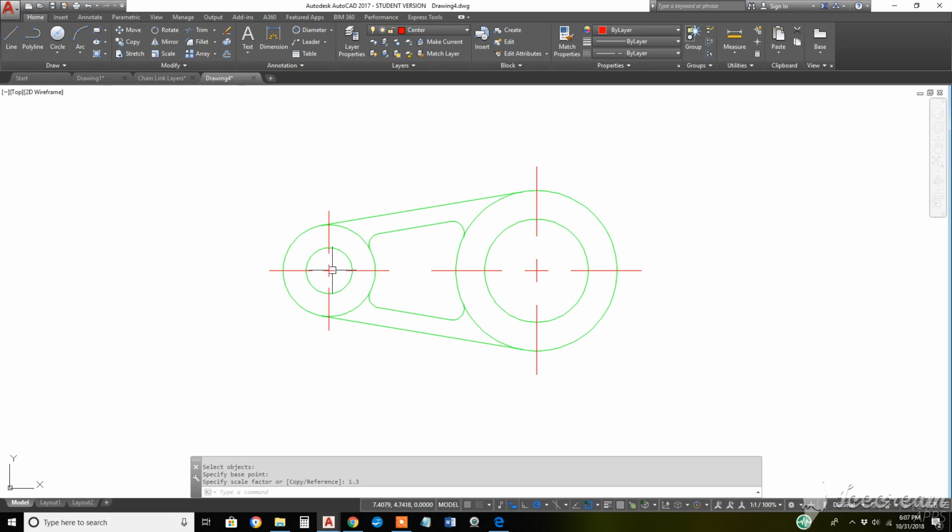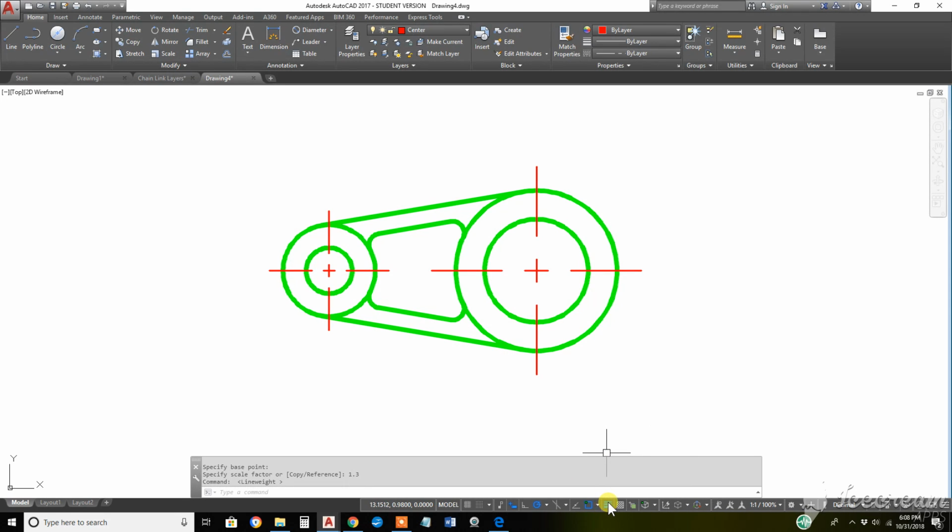So good. Center is the right, it looks good for the left side, and center X2 layer and line type look good for the right side. Again, you can get the warm and fuzzy by clicking the line weight display icon, and that's close to what it'll come out on paper looking like.